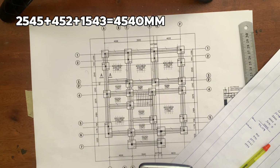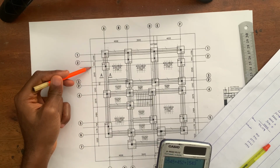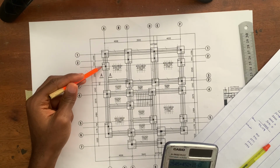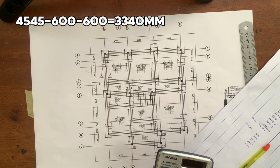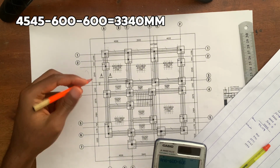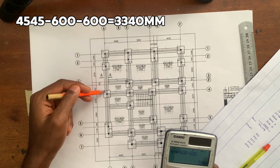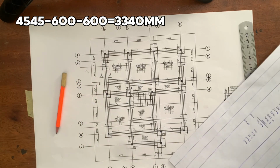So 2545 plus 452 plus 1543. That's going to give me 4540. So the distance from here to here is 4540. Now I'm going to be minusing half of the length of base type 2 and half of the length of this base type 2. Half of it will be 600, so 600 from both sides. When you minus it, we're going to be having 3340. So the distance from here to here is 3340. Now we're going to record.